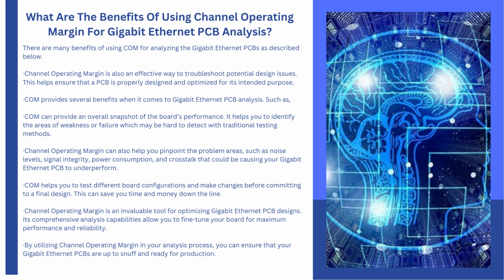COM provides several benefits when it comes to Gigabit Ethernet PCB analysis. Such as, COM can provide an overall snapshot of the board's performance. It helps you to identify the areas of weakness or failure which may be hard to detect with traditional testing methods. Channel operating margin can also help you pinpoint the problem areas, such as noise levels, signal integrity, power consumption, and crosstalk that could be causing your Gigabit Ethernet PCB to underperform.